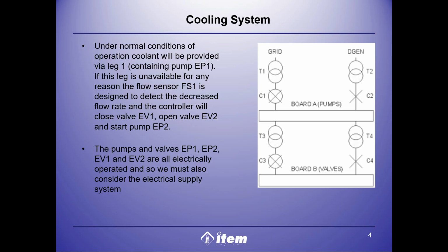This shared electrical network introduces major common cause dependency structures to the exercise. A loss of board A completely drops both pumps, while a failure of the external grid forces the system to rely entirely on the backup diesel generator. Keep these interactions in mind as you begin constructing your logic gates.